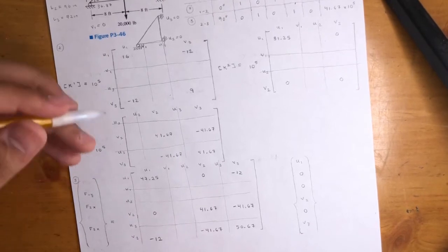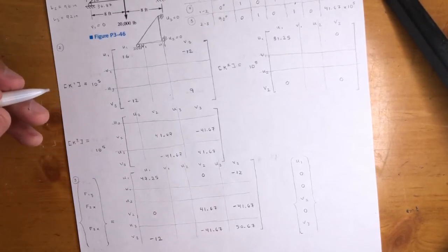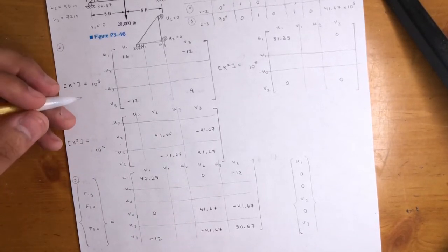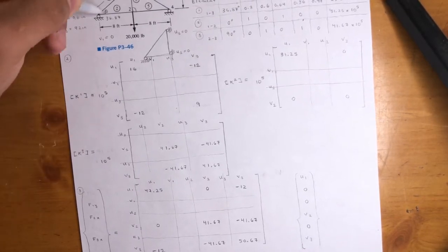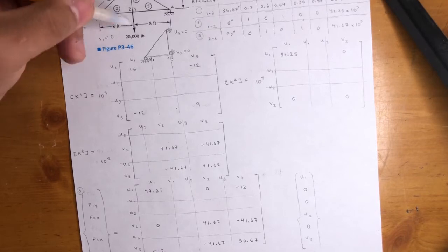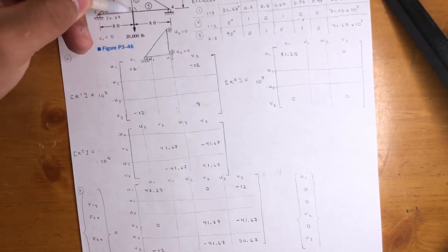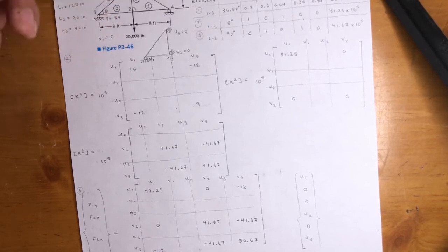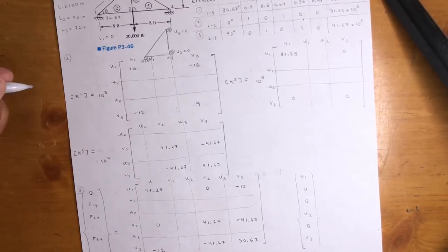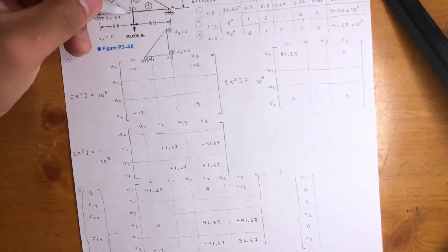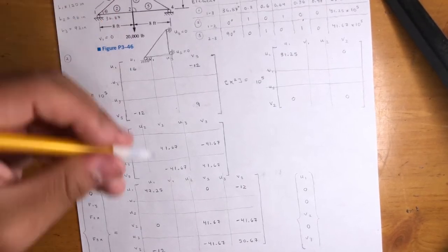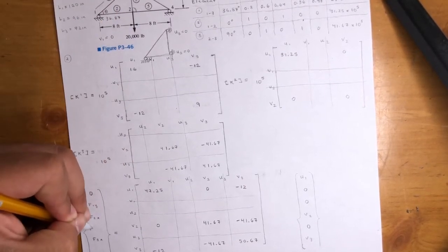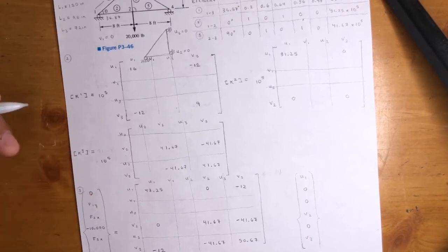That's kind of the trick to that too. It's a little hack I've noticed. But if you do that, at node 1 in the x direction, there's nothing being applied to it. Like in this case, we have 20,000 applied at 2. There's nothing in the x direction at 1, so that's 0. In the y direction at 2, it's 20,000, but remember, we cut it in half. You've got to remember that. That's going to mess you up. Negative 10,000. And again, there's a way to verify your answer at the end.